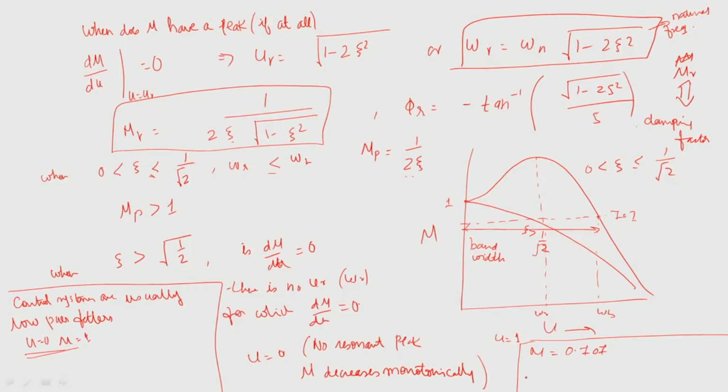and so M is just, I write down here, 1 over square root of (1 minus ub squared) squared plus (twice zeta ub) squared. Then a little approximation gives me that ub is minus 1.19 zeta plus some number 1.85. Okay. So, the bandwidth is also related to the damping factor of the system.